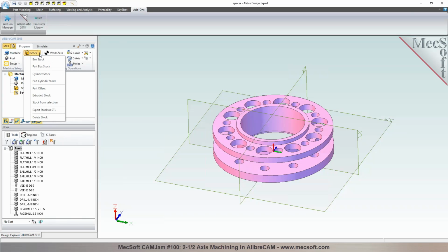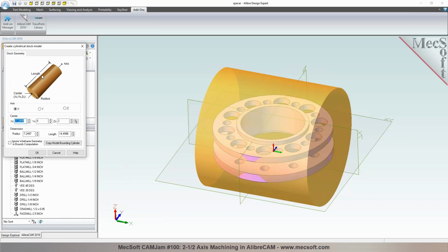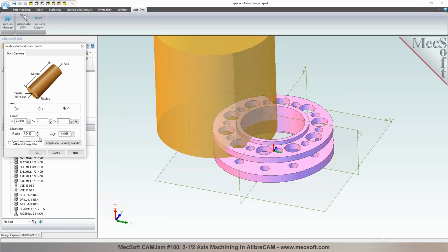The next step is you want to create your workpiece, the stock material. Right from the standard configuration, you can define box and cylinder stock. So for this particular part, since the part is round, I would go with a cylinder stock, unless you want to start with a rectangular piece of block and then cut around it. Right. So would you be starting with a round blank, like a cylinder blank? Yes, round blank. Okay, so we'll pick cylinder, and then we'll pick the axis as Z, and then if